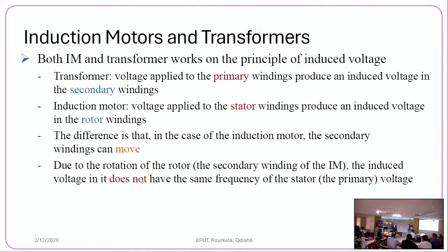Sir, in another method, voltage can also be induced in the armature so that will take the speed beyond synchronous speed. That is fine, it gives a super synchronous speed. These techniques are used in the induction generator. We are using wind turbines, so many wind turbines use induction generators. In an induction generator, the wind turbine drives and power is produced. If it is a slip ring induction machine, then from the rotor side also we can control to get power at the output at the stator.